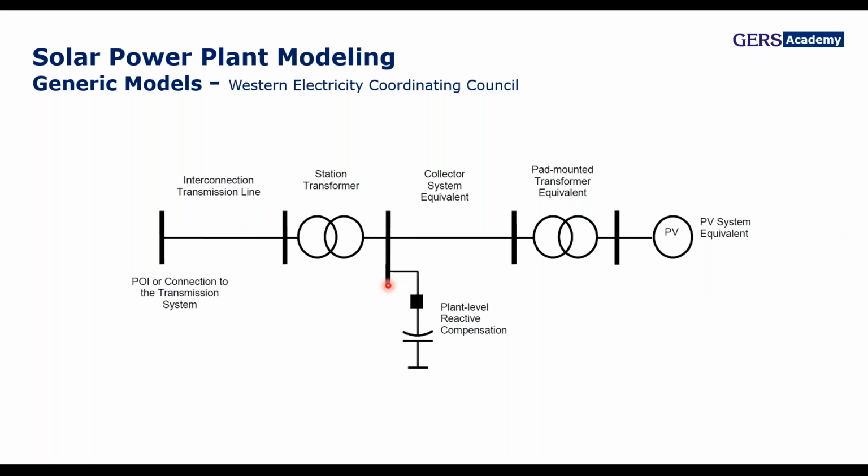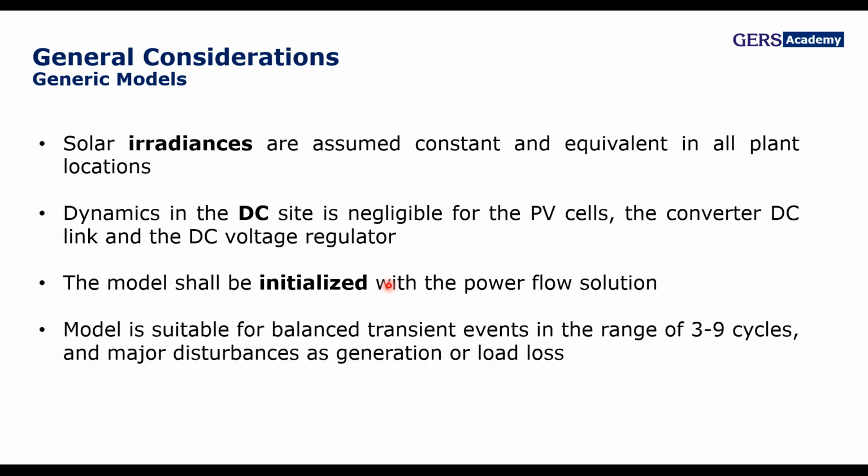Yes, remember that at least PV panels are considered not dispatchable, although Q in the inverters can be changed even when there is no sun. They have low short circuit contribution current, a lack of mechanical inertia, high bandwidth, and other specific characteristics, such as solar irradiance, that are assumed constant.